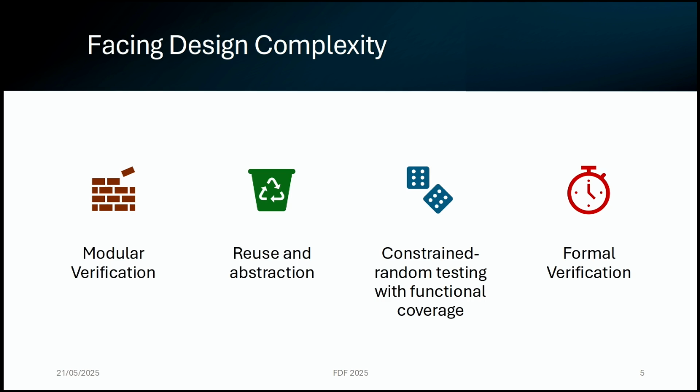So what I'm really telling you is to write a verification environment around all these, let's call them units, but that doesn't mean that you don't need to write a verification environment around the whole design. Because if you don't do that, you're not sure that the whole design is going to work. So you might be wondering, Simone, you're asking me to write a test bench around each unit and then a test bench around the whole thing. It's a lot more work. And I will say, yes, but.